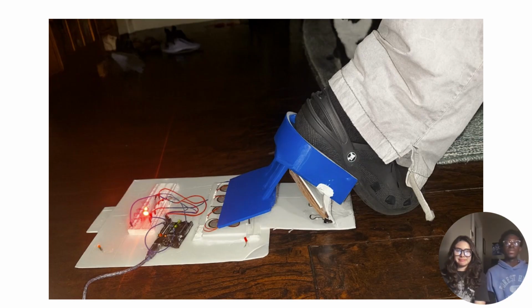Once the mechanical design was finalized, we assembled the full system. The pedal rotates downwards when the heel presses on it. This pushes down the integrated force applier rods onto our array of piezoelectric discs. Every heel tap compresses the discs, deforming them and creating a voltage spike, which then powers our LED lights we had provided to us.